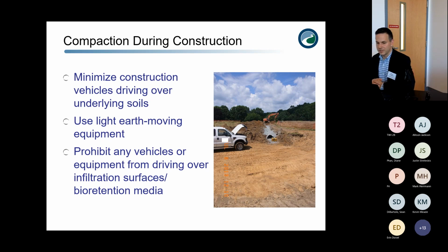Compaction during construction, this is another issue we often see. I put a little block on the truck so you wouldn't see the name of the company, but that's a pickup truck that's driving on the bottom of an infiltration basin before they put the soil down. A lot of times, folks from construction companies, maybe they haven't worked on this type of project before, don't know what they should be doing. That's a nice place to drive.